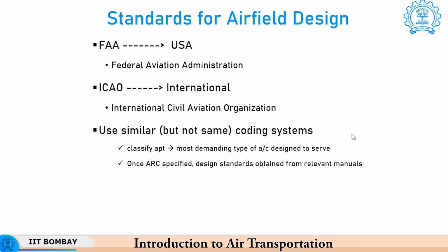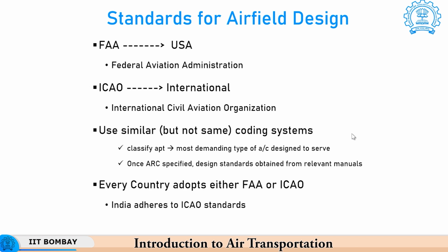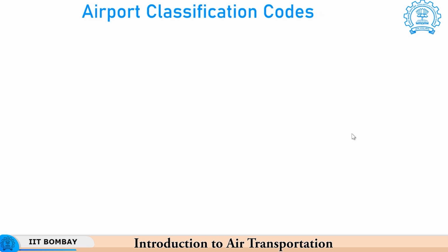So, what should be the gap between runway and taxiway, etc., all that is fixed based on the aerodrome reference code. Every country will adopt either FAA or ICAO regulations. We in India are adhering to the ICAO standards. Let us have a look at airport classification codes.